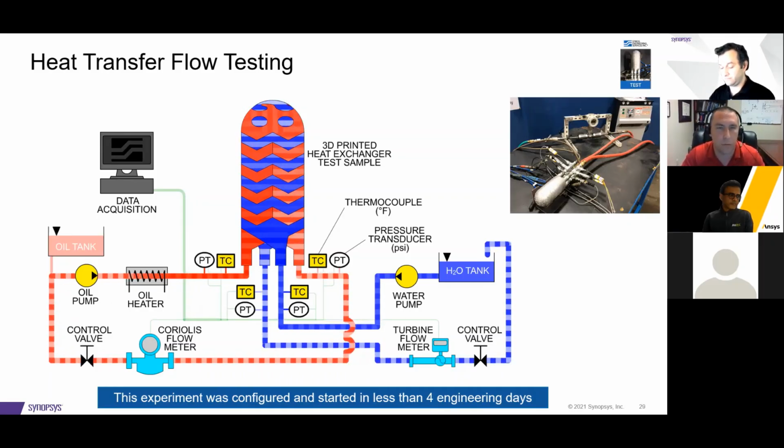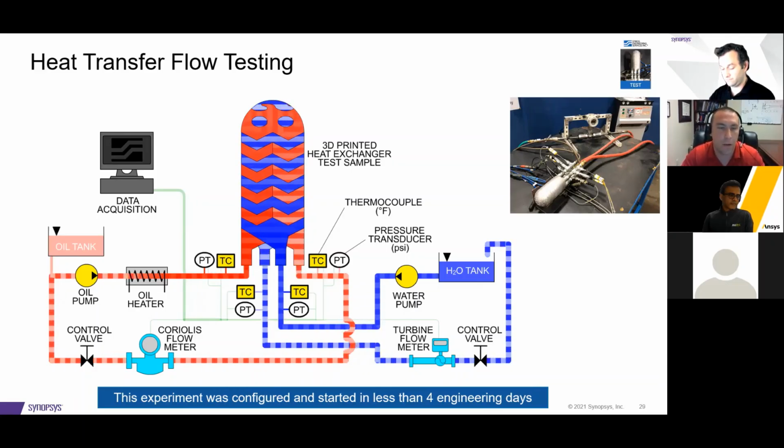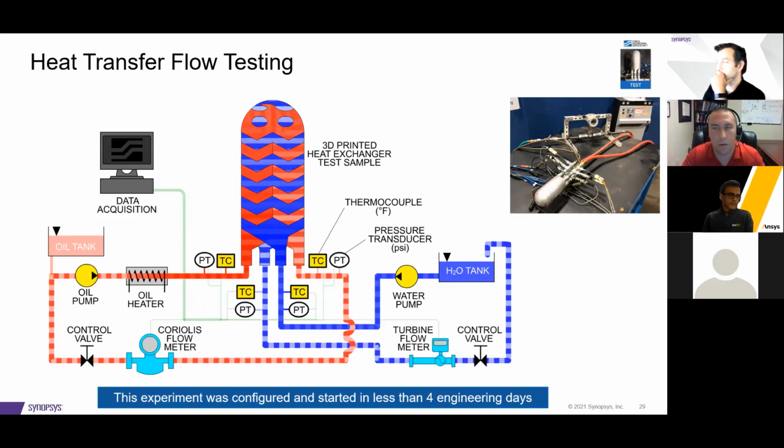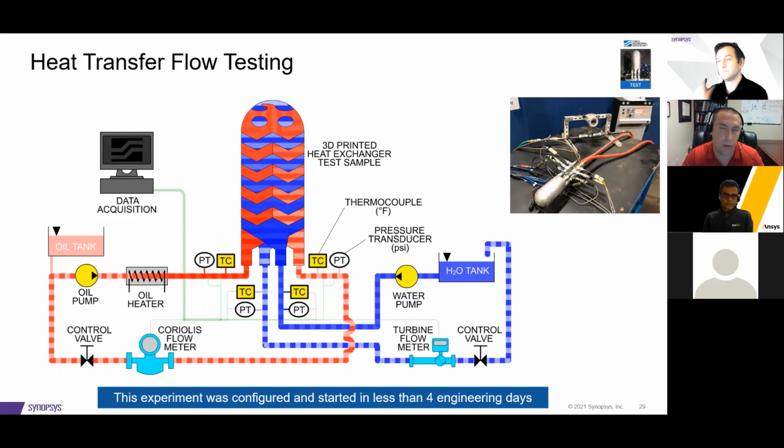And so for that, it was important that we took a look at varying and setting up our flow rates in order to match Reynolds number and Reynolds number times Prandtl number, so that we can get some similarity between the full-scale real-world test and the simulation.